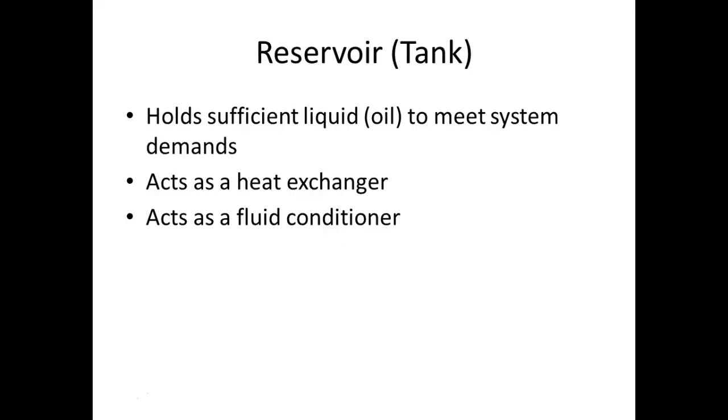Reservoir holds sufficient liquid to meet the system's demand, acts as a heat exchanger, acts as a fluid conditioner. What fluid conditioner? Anytime it comes back, it falls back into the tank. A lot of times it creates bubbles, and we have to have some way to make sure we don't get any air bubbles in the system. Because liquids are considered to be incompressible. They do compress a little bit, but it's beyond our understanding. And if you get air in there, air is compressible. So that creates a lot of problems. Anybody that had to bleed brakes in a car understands that. Some way to get rid of the heat.